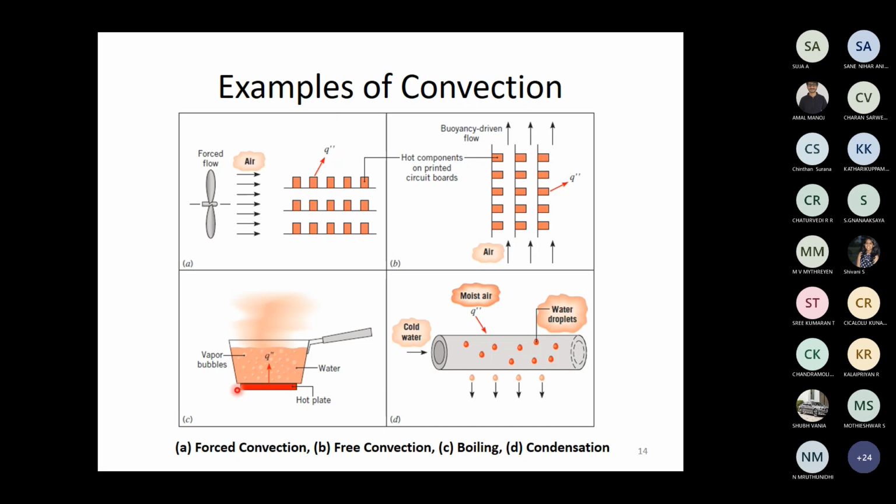And you can see here, as the heating takes place, vapor bubbles are formed initially on the bottom surface of the vessel. Initially, the bubbles will be smaller in size. Later, the bubbles will increase in size, and then they start rising. In the process, bubbles also join together. They rise to the top, and at the top, some bubbles burst. That is how some convection currents are set up during the boiling process. We have an experiment in our lab where you will observe all these phenomena. Because of this movement of the vapor bubbles, boiling is also treated as convection.